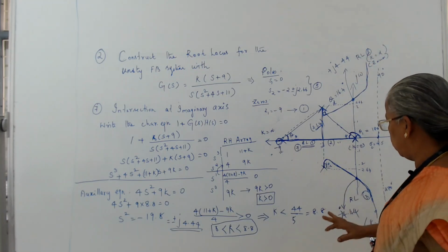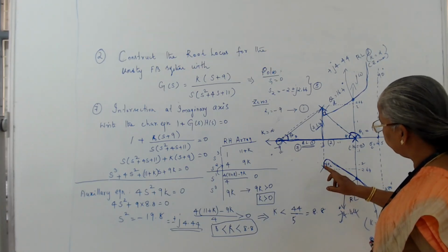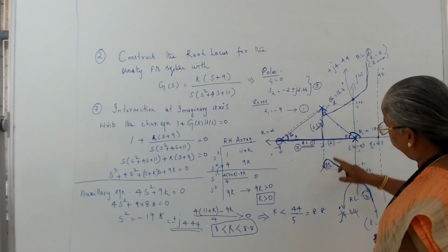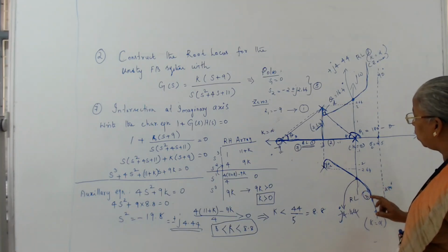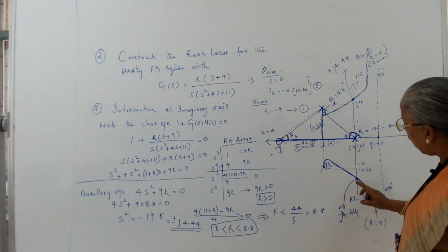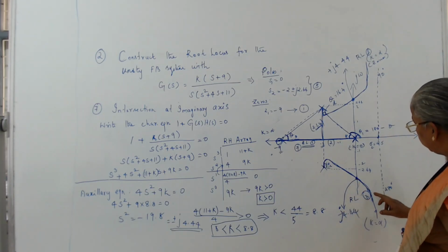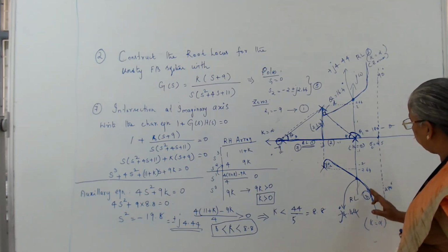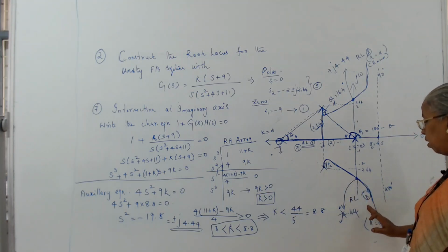Okay. Now root locus 3: another pole is at minus 2 minus j 2.64. So from here it will start and go to this point, that is an angle of 16.4 degrees, and then it will travel towards the asymptote and intersect the imaginary axis at the point of minus j 4.44, and it will travel towards the zero, which is located at infinity, and follow the path of the asymptotic line. So this is root locus number 3.